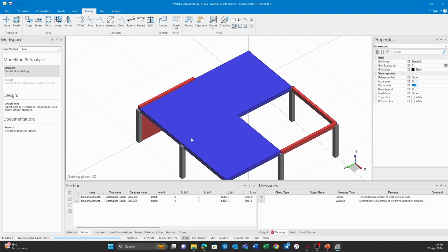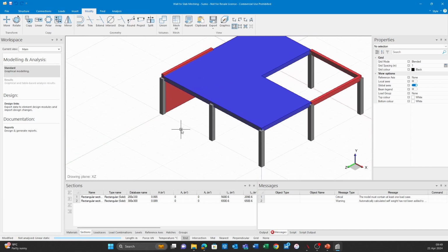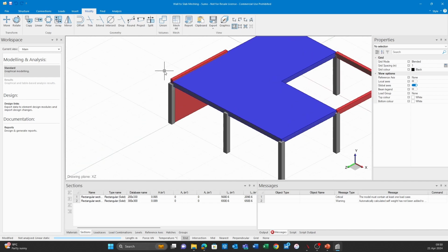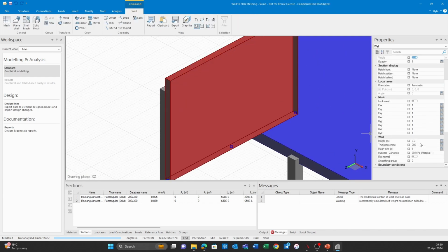One of the things that we always want to do is model as accurately as possible. Already when we get to an analytical package, that becomes incredibly difficult because of how it works. Everything works on centralized planes, shear centers, and center lines. In reality, our buildings aren't modeled like that, if you think of how you'd model in Revit, etc. So here we've got a wall, and this wall extends beyond the slab, so it's a 3.3 meter high wall.